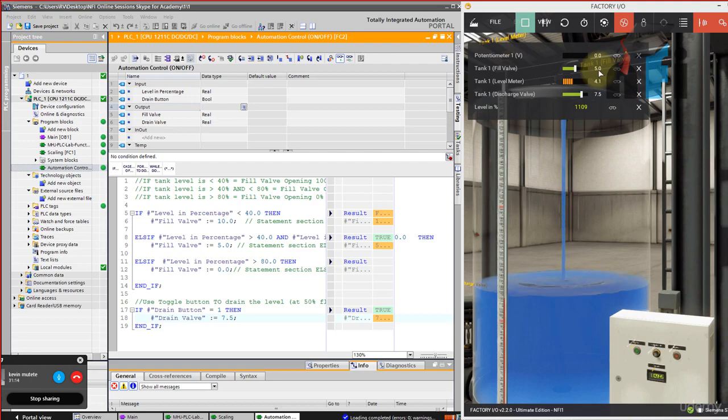You see this thing? This is one of the disadvantages of this on-off control, which is why we want proportional control, because we have an on-off situation here. Are you getting me? Yes, sir. So this situation we can avoid using proportional control because this is harmful for the equipment. If you make something go to 100% then 50%, we have to have a proportional control of the valve, which is a smooth operation. So to avoid this situation, we go for proportional control. But before going to proportional, I want you guys to understand these loops, if and else, otherwise it will be difficult for you to proceed.